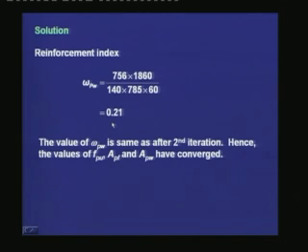That means we have converged to a value of omega Pw which is not changing substantially beyond the third iteration. Hence, this number of iterations is sufficient, and we can use the values of Fpu that we have got to calculate the ultimate moment of resistance.